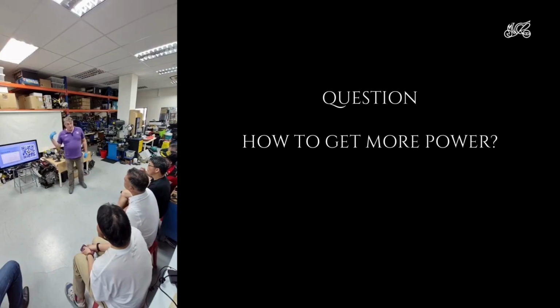If you do it with Webers, then sure, you can get the same maximum power, but the car just won't idle right, because of not just the jetting, but also the weird airflow when you've got lots of overlap in the cam. So yeah, and of course now it's got super easy with your ECU, because if you want more fuel, you just change the chip.